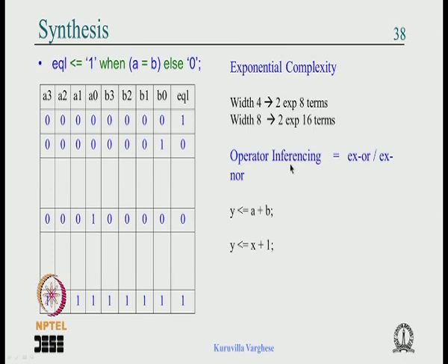A synthesis tool looks at the operator, and the operators are already written with exclusive OR gates, so that is how it is synthesized. Similarly, if somebody writes A plus B, it is not that a truth table of the adder is written and you end up with a carry lookahead adder or something like that. The plus is implemented in a simple way as a ripple adder.